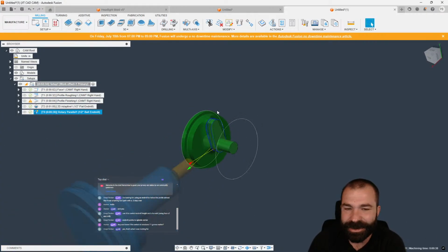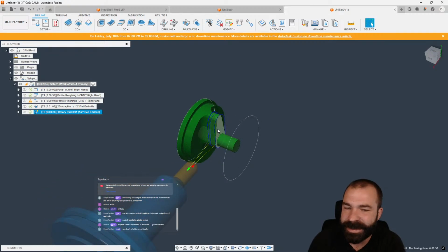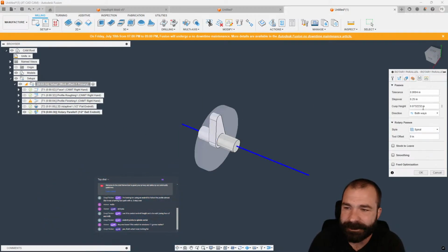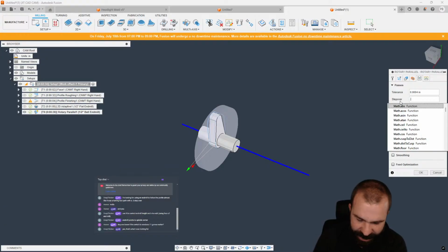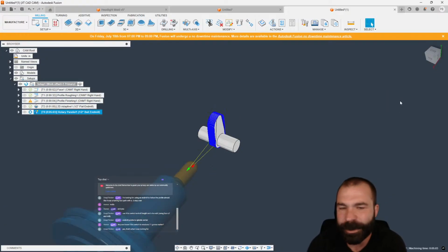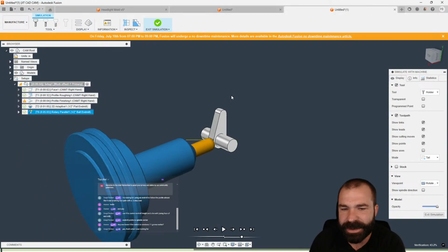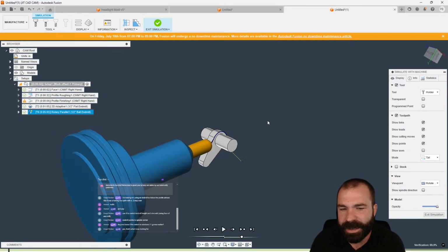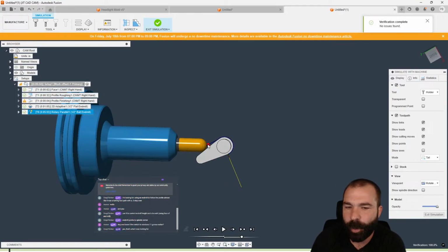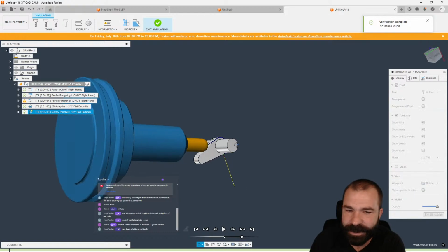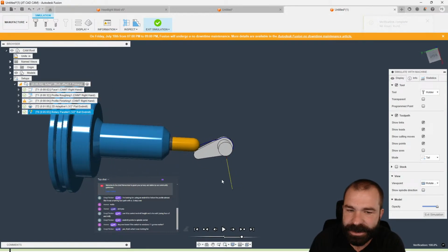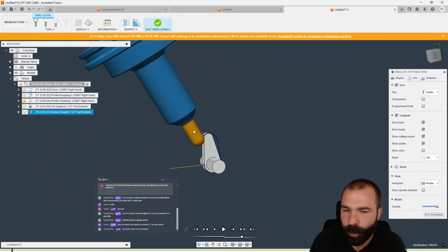And the good news is, as you guys can all see, now that we've got it contained where we want our blue lines, we of course can make it much nicer. We could add additional passes, change our step over, whatever your end goal was with that toolpath. And now, because it is a ball end mill, this is very important to remember, the ball end mill is always pointing at the center of rotation. And when we look at that, as you're going to start to climb up and down that part here, you're going to notice that tool is always pointed at the center line of rotation, right? So we're not actually perpendicular to the surface here. We are climbing up and over, and now we are up milling and down milling. Might be a little brutal on your tool.